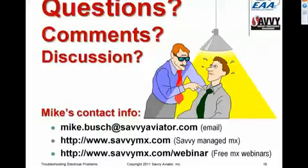So it does put a load on the battery. It's not a very big load. Normally, I would recommend having the alternator on for start, among other things, for 2 reasons. One is to prevent the possible scenario that you will forget to turn it on and go flying with no alternator. And the other is that if you start the engine and bring the RPM up and then turn the alternator on, it puts a certain shock on the alternator to have the field turned on while it's rotating rapidly.